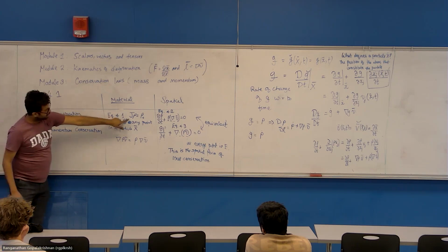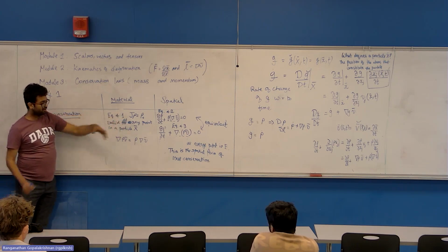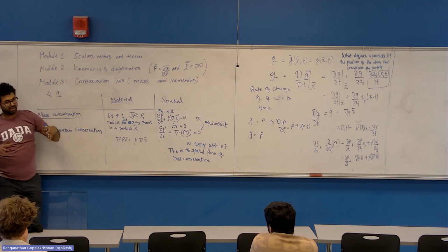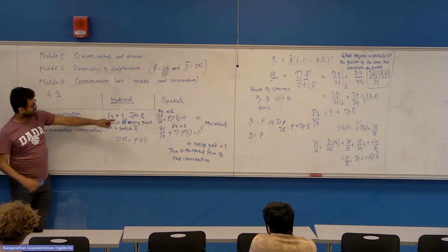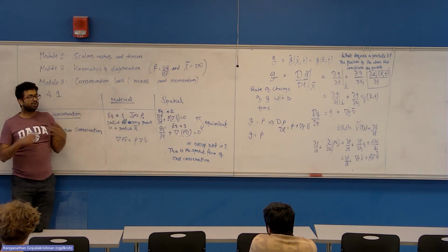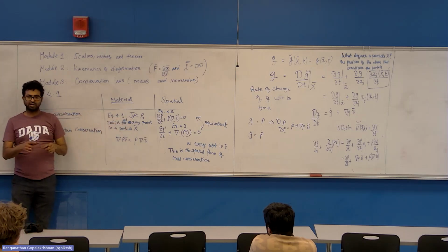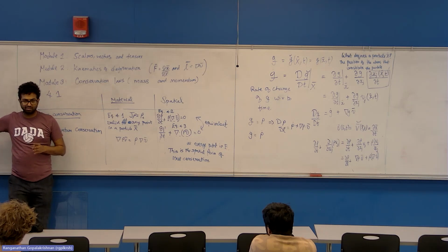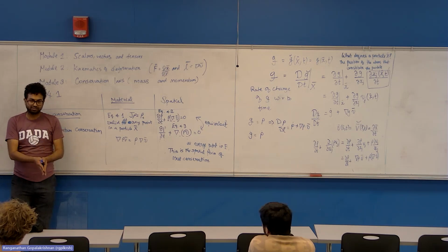This is applicable at any point. And if you are given some sort of constraint about the material, if the J value is calculated through the deformation mapping and you know the J value, this equation is really simple. It's like saying at every point, J is just the scaling factor between the reference density or the density at that point in the reference configuration versus the current deformed configuration.